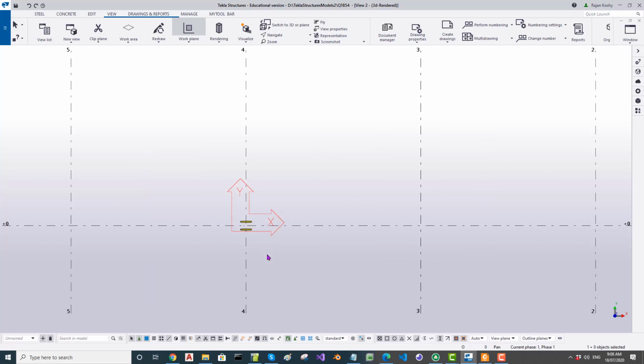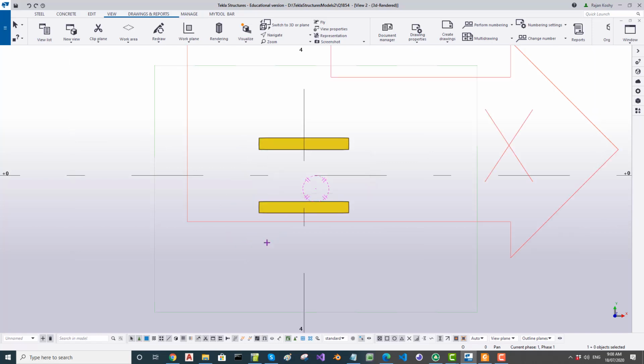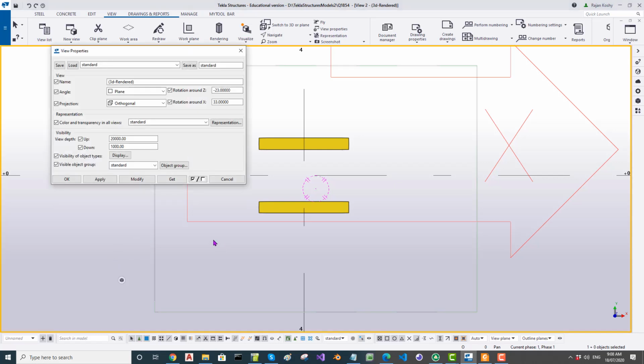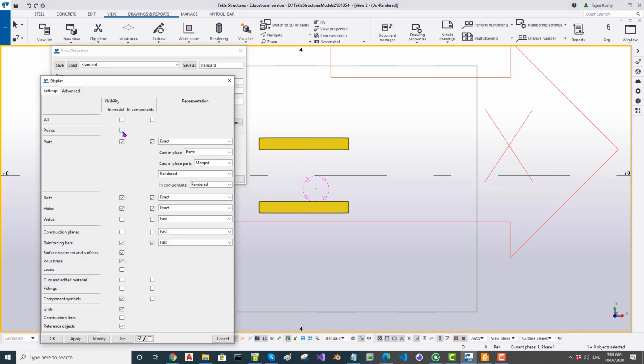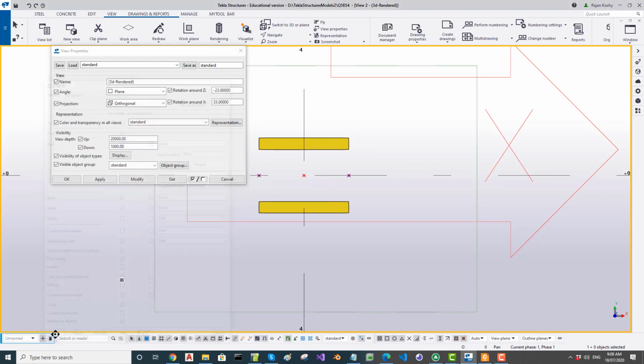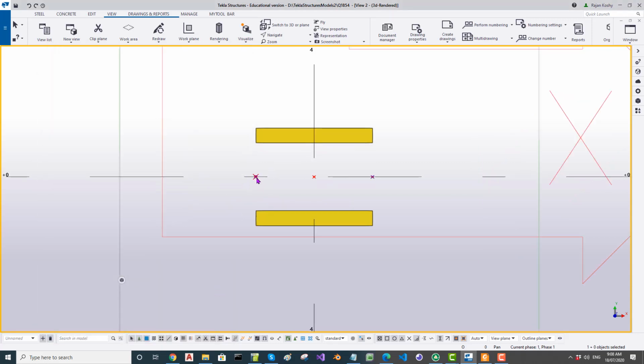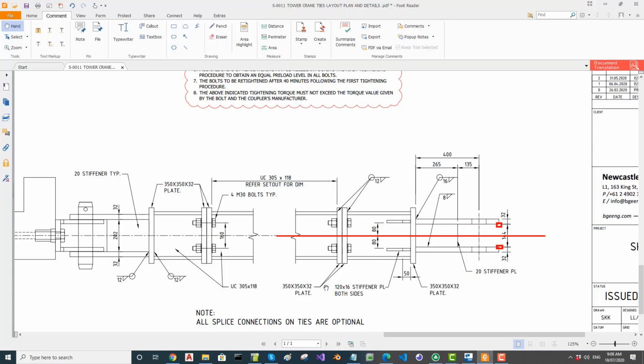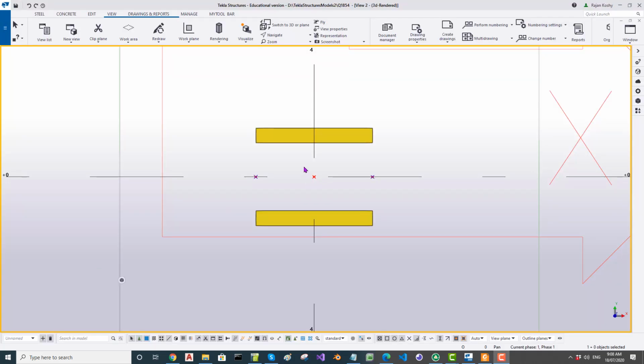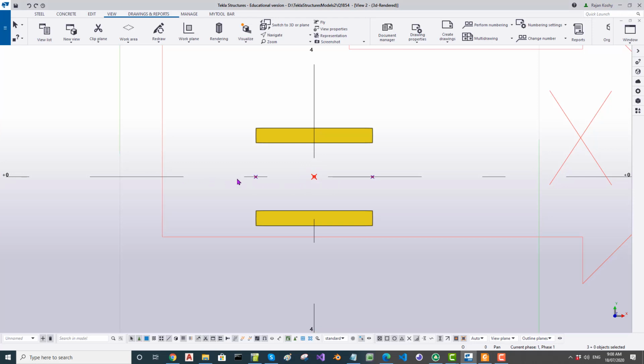So it is too tiny. Again, I'm going to set my work area using 2 points so that I can see properly. So that's the view. But if I can't see the points, I'm going to switch it, modify and apply. Okay, so these are our points. And this is 125, and we want the plate at 350. The plate is 350 by 350. So I can copy these points by 175 both ways. So then let me do that way.